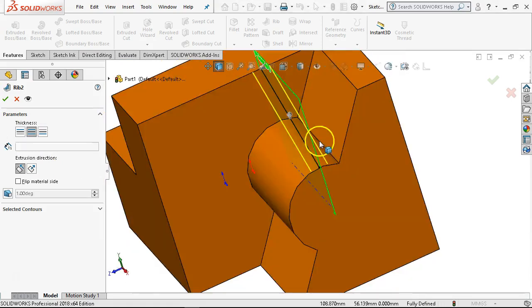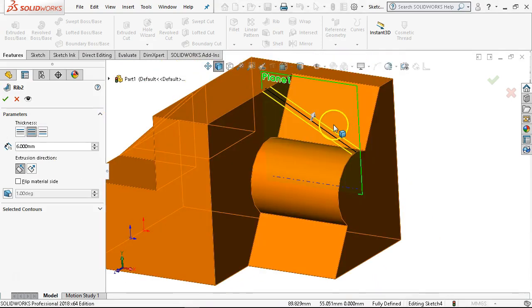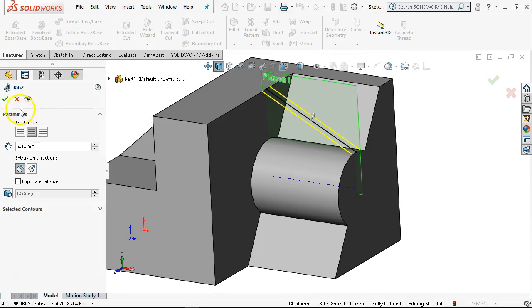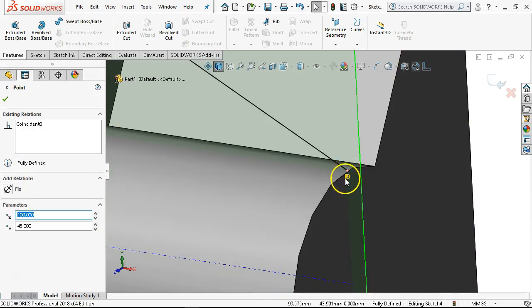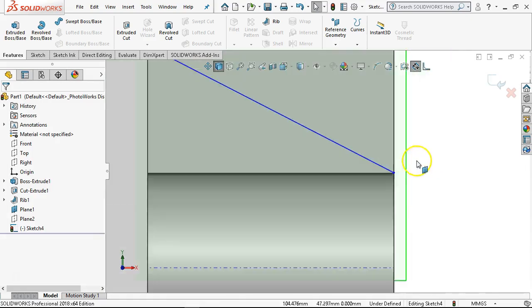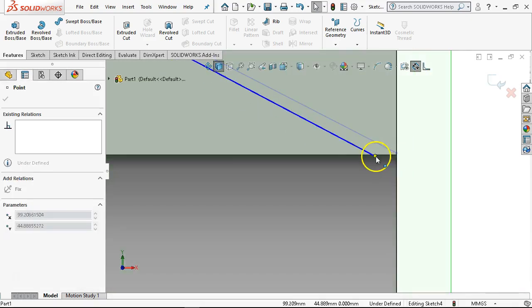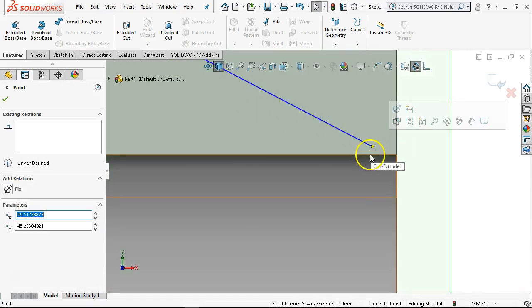And failed to create rib feature. Well, that gives you a lot of information as to why it failed. All right. Why it failed is that as this surface is falling away, it can't calculate that linear edge, the top linear edge of the rib. So let me get back normal too. And so the solution is to give it, let's see if we can find that silhouette edge.